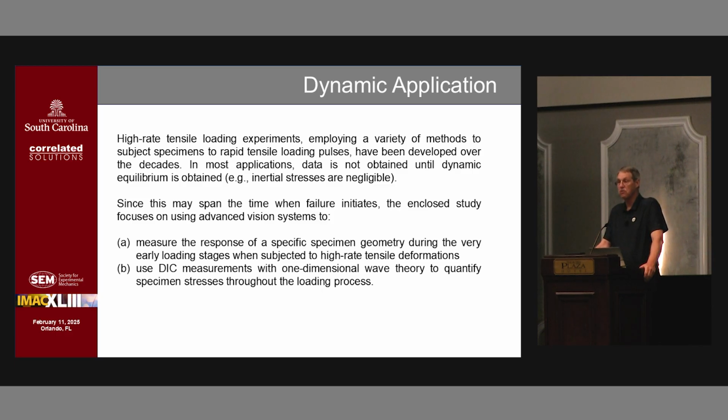I want to know what's going on with various stages, and can I predict the inertial stresses? And when I say predict, in reality I mean measure. Physically measure the inertial stresses. So let's see what this is going to look like. And to do that, of course, we're going to have the one-dimensional wave equation. Kolsky didn't develop that. It was done by others, but the Kolsky bar system, or the split Hopkinson bar, is the one we use today.